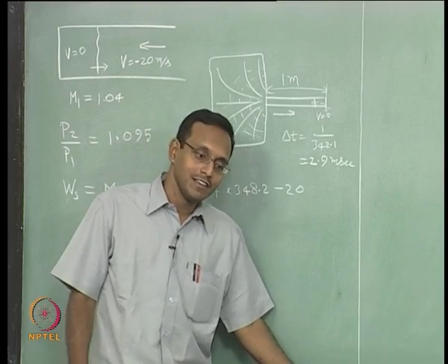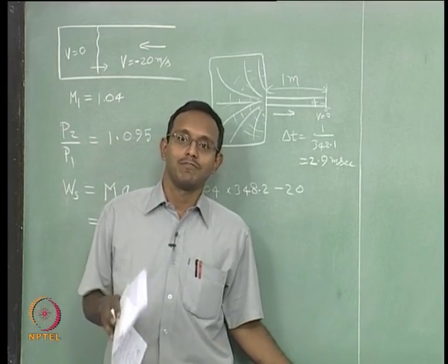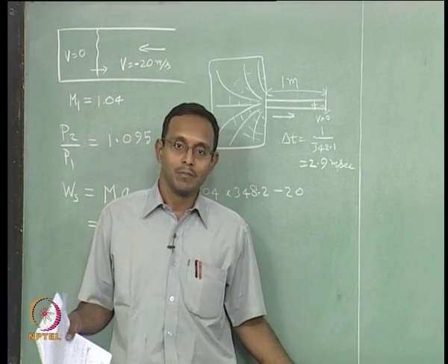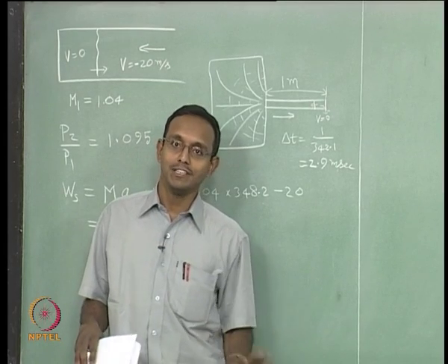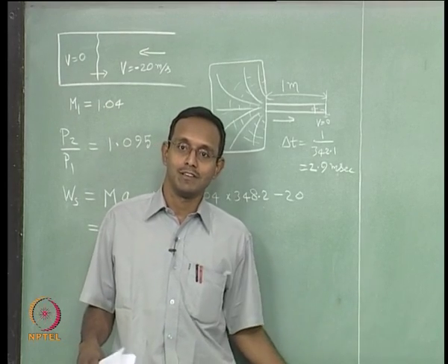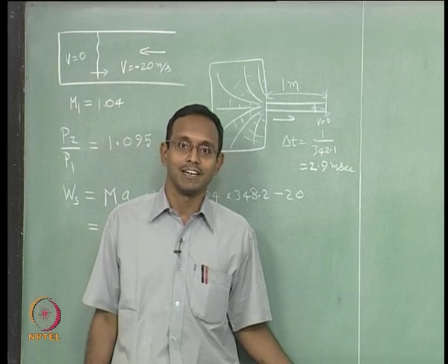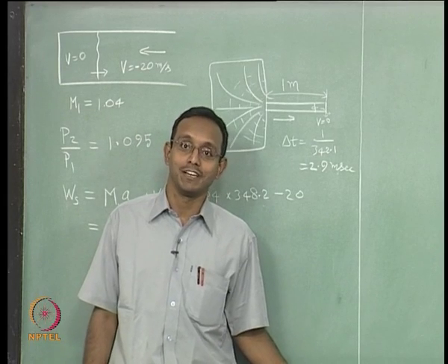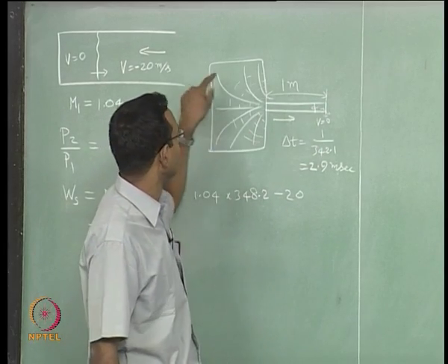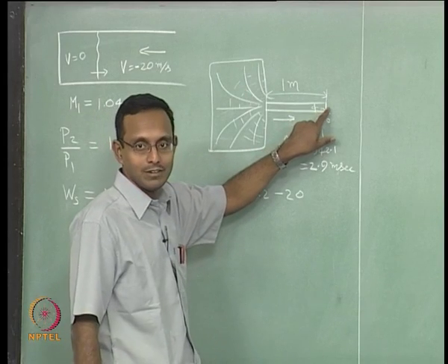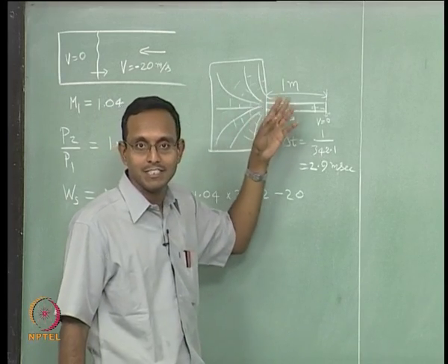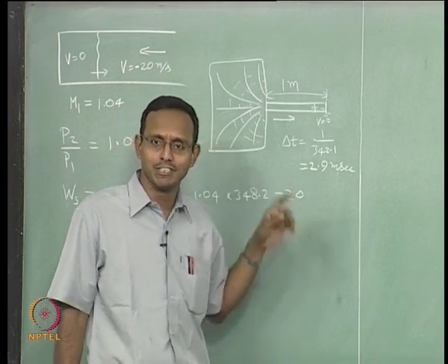I want to say that when the flow is unsteady, compressible flow field can happen anywhere at any velocities, because the gas can adjust only through compressible effects, only through compression waves or expansion waves, which are all compressibility related effects. That is the only way a fluid can communicate from one point to another. The only way that the fluid inside this tank can know that there is a wall suddenly appearing is through this shock, and that is a wave that is going through, it is a pressure wave, it so happens it is a high pressure wave.